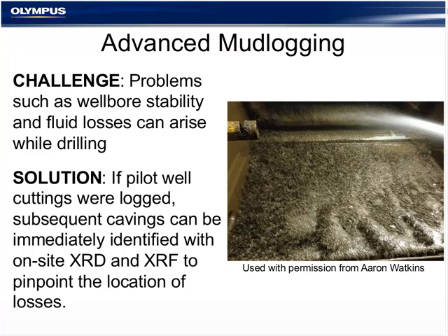An abundance of cavings of this type are strongly indicative of borehole instability caused by underbalanced drilling. The differential pressure allows swelling of the formation adjacent to the borehole, and therefore the appearance of splintery cavings is often associated with other indications of borehole instability, such as an increase of torque and overpull and drag while tripping.